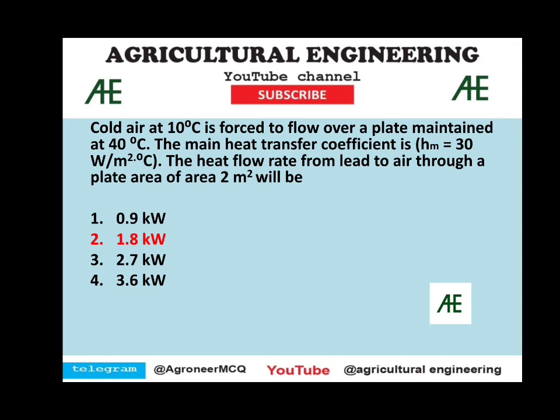A is area, which is given as 2. 30 into 2 is 60, and the temperature difference 40 degrees Celsius minus 10 degrees Celsius, we will get 30. So 60 into 30, we will get 1800 watts, and now we have to convert it into kilowatt. So we will get 1.8 kilowatt as the answer.